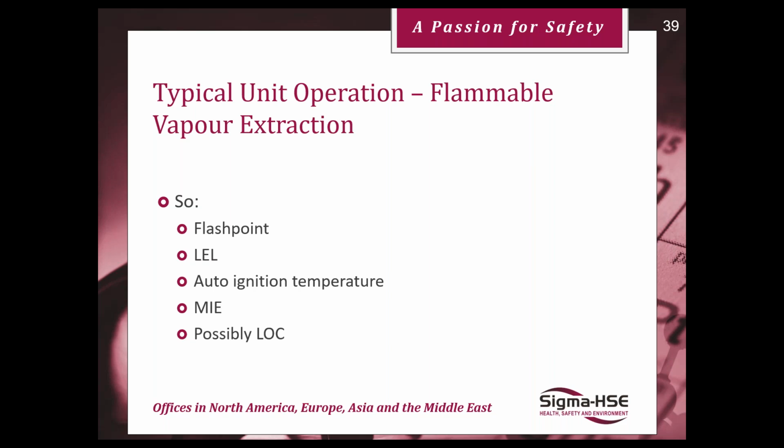But again, flash point is important because that will determine how much vapour is given off. With LEL concentrations, if we can operate below the LEL by providing sufficient ventilation, or in fact operate above the upper explosive limit, that can also keep us safe.